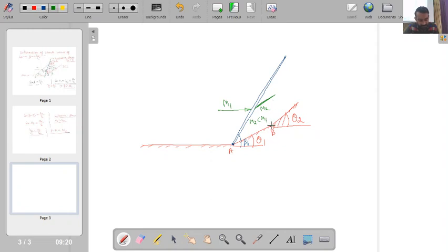Now if any wave starts at point B, I have already seen that after the deflection, if I have the presence of a wave, then beta minus theta is less even than the Mach wave which is forming at point B. But because point B has a sharp corner, despite the Mach wave I will have formation of another oblique shock wave. As I know that the strength of an oblique shock wave is greater in comparison to the strength of the Mach wave, I can say that angle beta 2 will be greater than mu 2. Because mu 2 is the angle for any Mach wave at point B, and because it has a sharp corner, despite the Mach wave I will have the presence of another oblique shock wave.